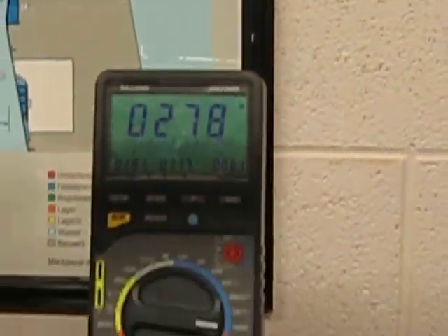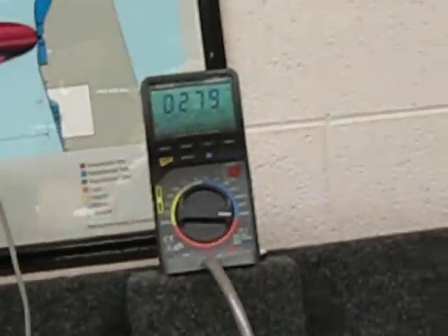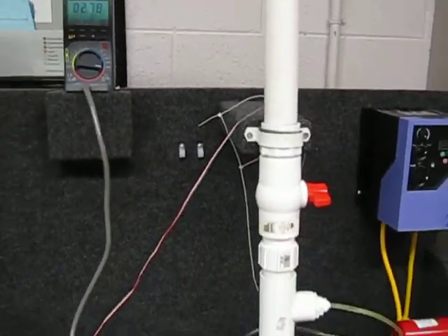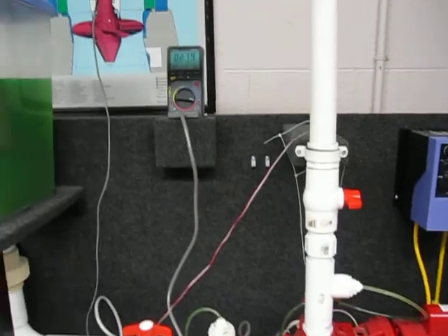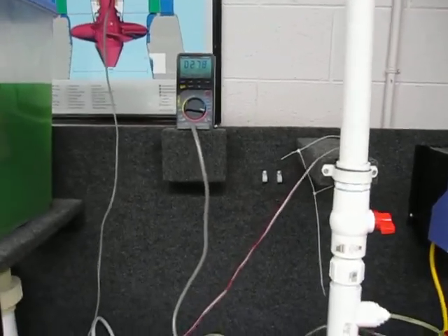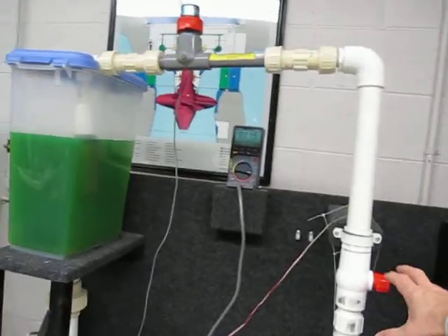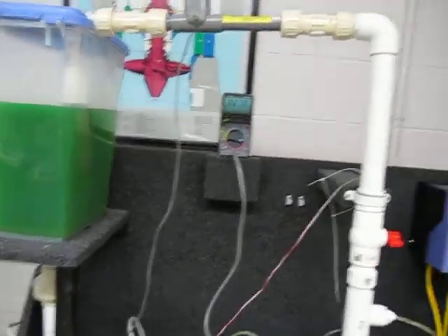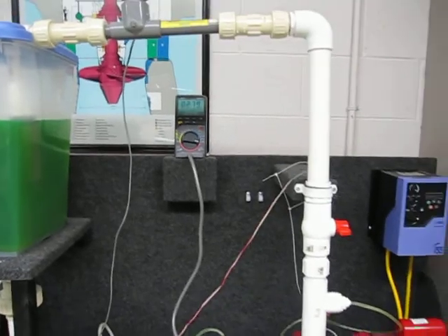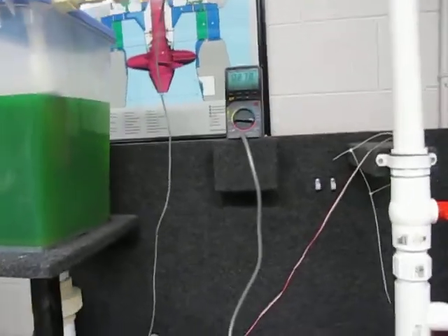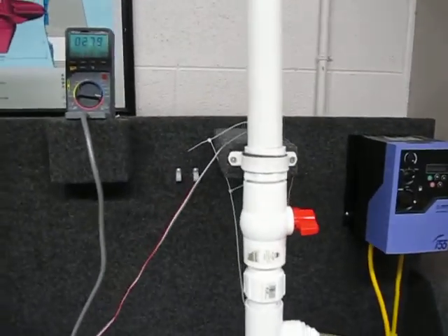Well, that's the first phase of the experiment. We've used the throttling valve here to control the flow. One of the things we will notice is this is not a very efficient way of doing things, because we're putting a restriction on the system that's going to make it work harder, but it's actually putting less energy into the fluid. The next step then is to run off the variable frequency drive.